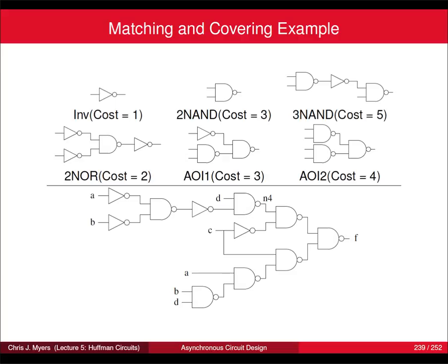Okay, so that's technology mapping. So this is using real library gates now. Okay, and again, technology mapping is a big subject of the logic synthesis class, and that would be hazard free. So I started, remember, with my original 2-level implementation, and then I derived a multi-level implementation, and then I did technology mapping, and all along the process, I was very careful not to introduce hazards. So I had no hazards. I eliminated the hazards in the 2-level step, and I just was careful not to introduce them as I went through the multi-level step.